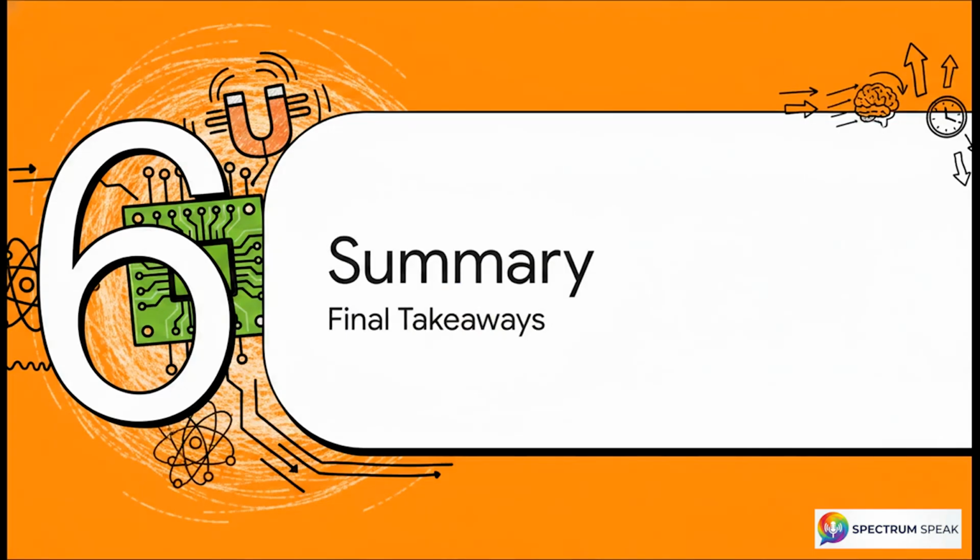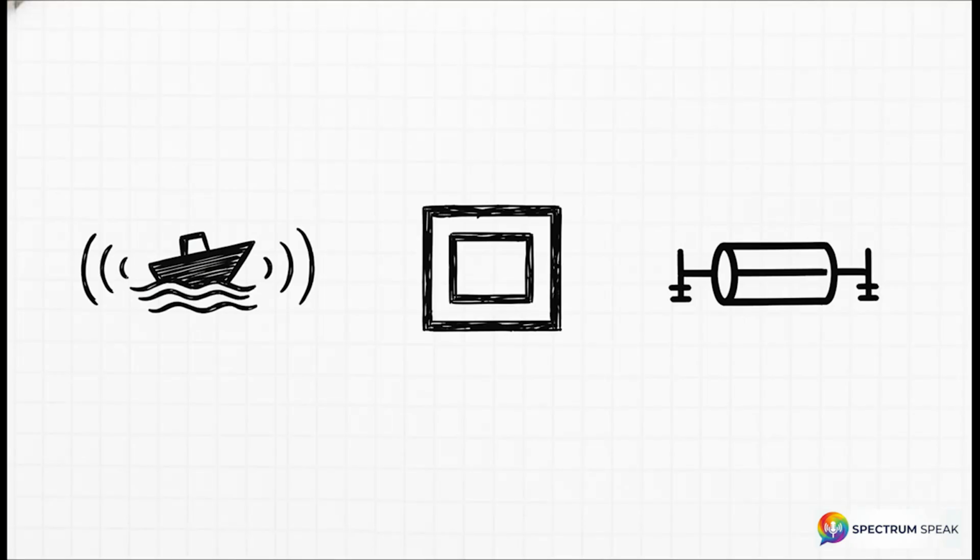All right, bringing it home with section 6, a quick summary and our final takeaways. Number 1. Always remember the boat analogy. Mutual inductance is simply the ratio of those magnetic ripples hitting your circuit divided by the current that caused the splash in the first place. M equals phi over I. Number 2. For nested coplanar loops, all that intimidating math elegantly simplifies down to M equals 4 times 10 to the negative 7th times the natural log of B over A. It is heavily dependent on your geometric spacing. And number 3, our massive gotcha, a non-magnetic shield grounded at only one end provides zero magnetic protection. You have to ground it at both ends to allow those countercurrents to flow.